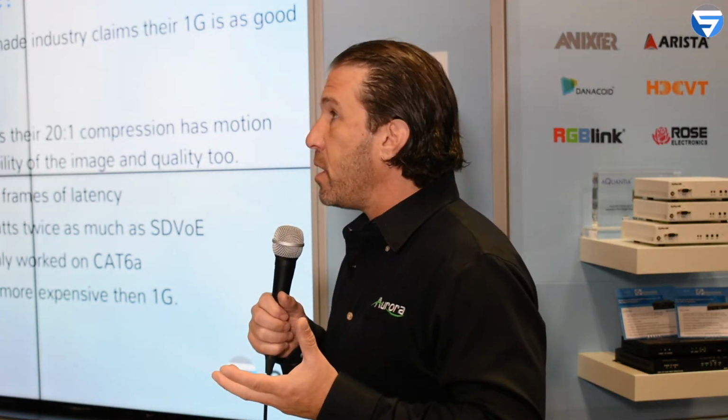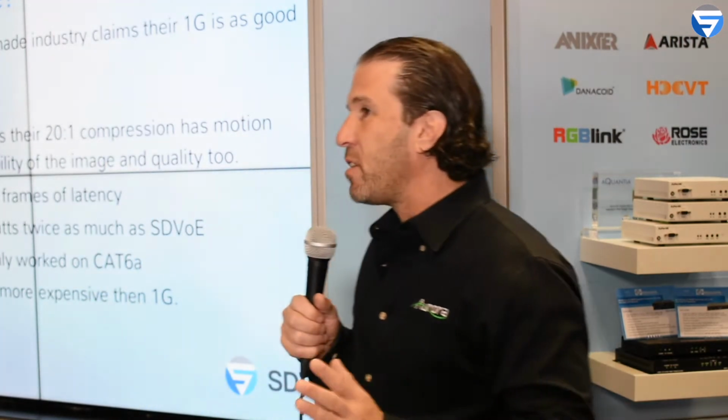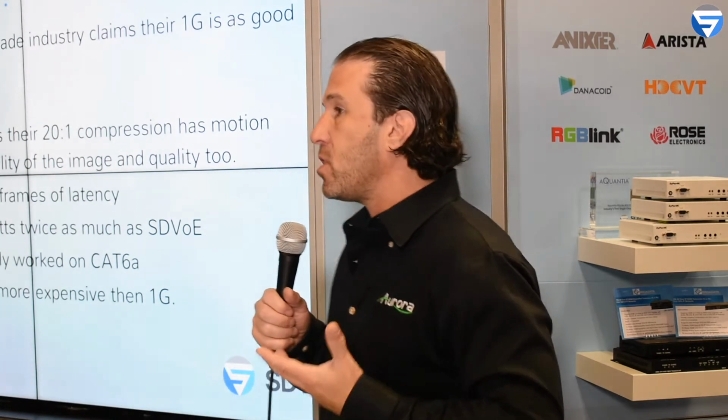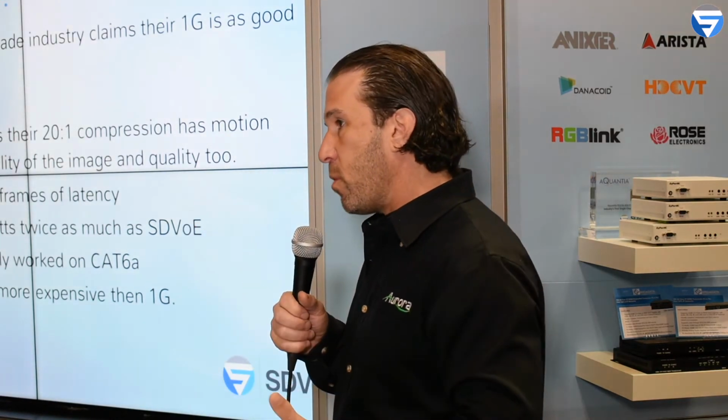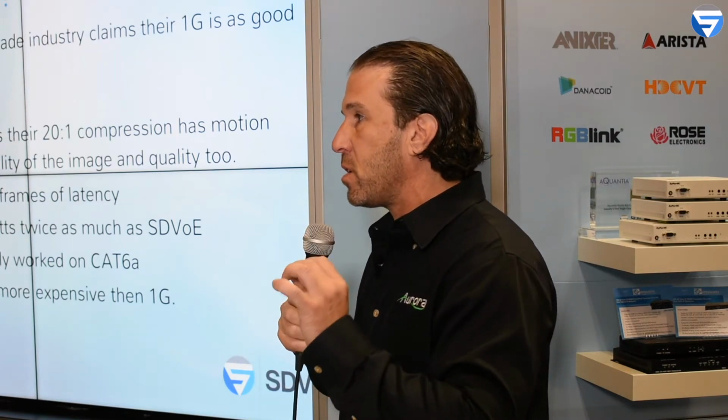SDVoE, probably by, I'd say, Q1 of next year, they'd have to answer this more than I can, but you're looking at products that are going to potentially run on standard PoE. Forget about even PoE++ or PoE+. We're talking standard PoE. We're going to have products that are going to actually be able to live inside projectors or displays or media players, products that have no fans, no heat sinks, because it's running cool enough to just work on its own. And the price points are also going to drop simply because the technology is now burned into an ASIC from a semiconductor company.